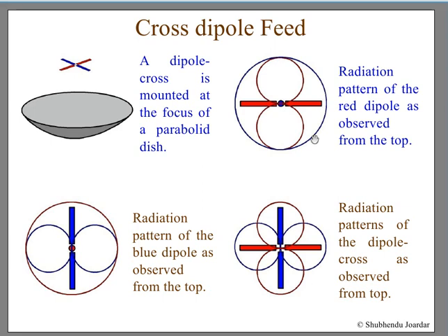So here is a dipole. You can see the pattern of 8 here. If you have a reflector around this place, at lambda by 4, then this portion will be reflected back and overlap this one. So effectively this will have a pattern like this, and on this side it will not have.